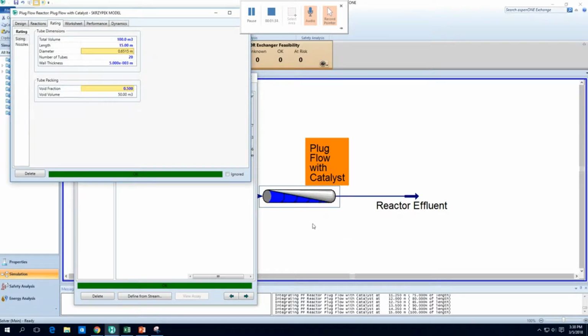Let's put it at 18. And 18 is about 50 kilopascals, and that is, to me, pretty acceptable. Yeah, and the diameter is about 0.6 meters. So if I just put it at 15, it'll be like 0.65. Let's put it at 10. I mean, that's a pretty reasonably sized reactor. Okay, 10 kilopascals. Wow, that's good. 10 kilopascal pressure drop across the whole thing.